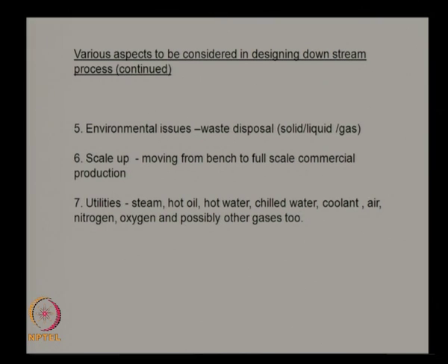To continue further, what type of waste I am producing after I do the downstream purification or downstream isolation? When I am isolating a product, whatever is left behind is a waste. Does the waste contain solid? Does the waste contain liquid? Is the waste toxic? Can I just dispose it in the environment, or do I need to do any treatment?